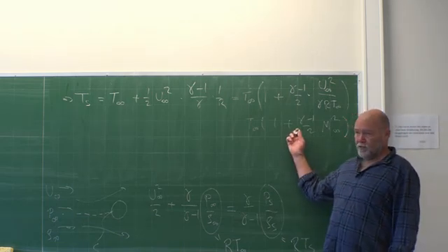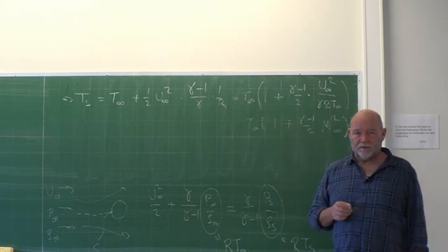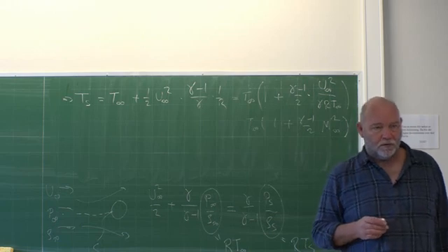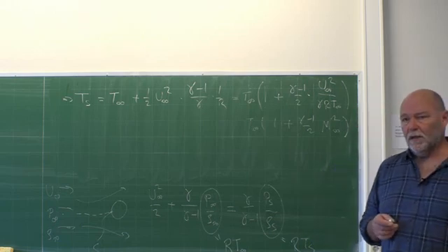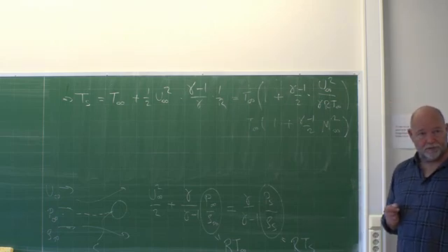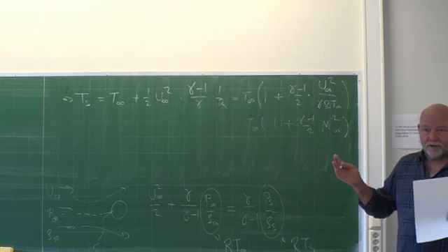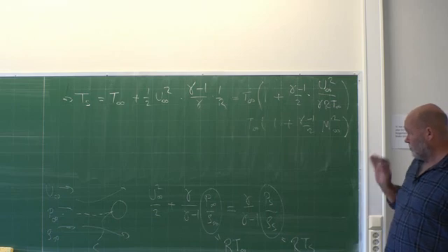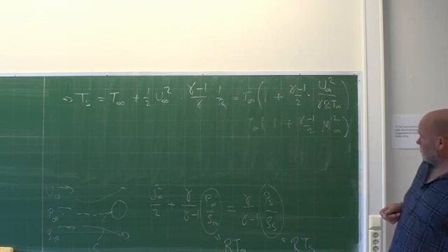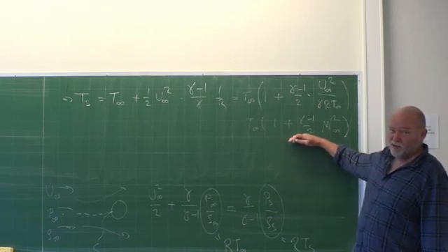Well, first of all, the theory doesn't apply. When you have a Mach number of 25, then it's not a continuum anymore. So you have to use kinetic gas theory and stuff like that. And also, when you hit the first air molecules, nitrogen is going to dissociate and sort of steal the energy away there. So no, they don't melt, but they need some heat shields.